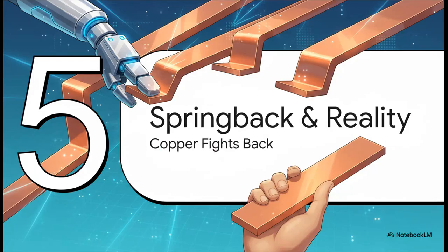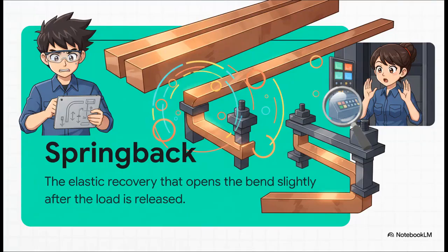And that brings us to our final section, springback and shop reality. You know, you can do all the perfect math in the world, but you have to remember that copper has elasticity. Springback is the elastic recovery that opens the bend up slightly after the heavy forming press releases its load. Basically, the copper literally fights back. Especially when you're dealing with hard-drawn copper and large radius bends, the material is going to relax and open up to a slightly larger angle the literal second the operator lets go.